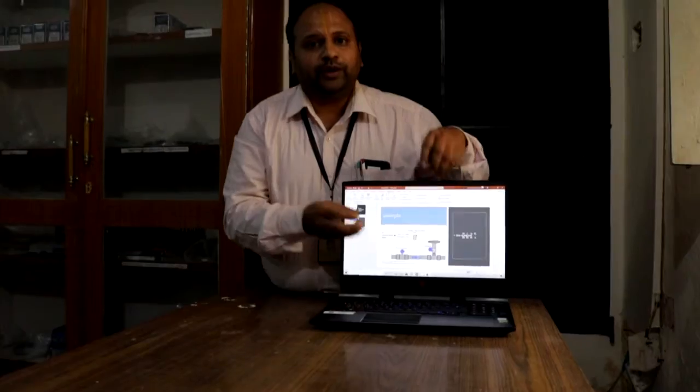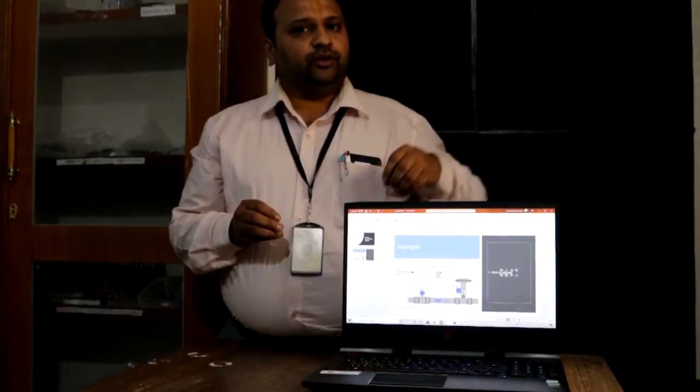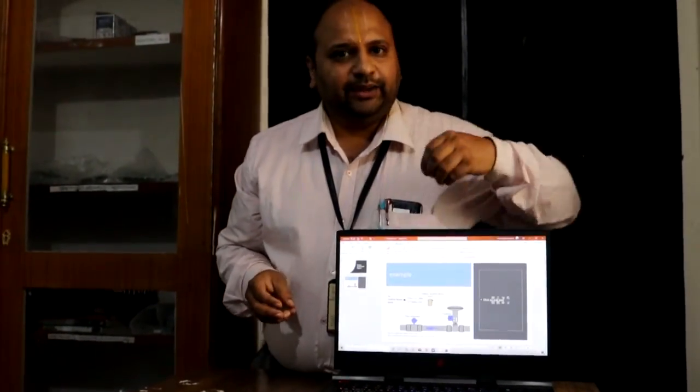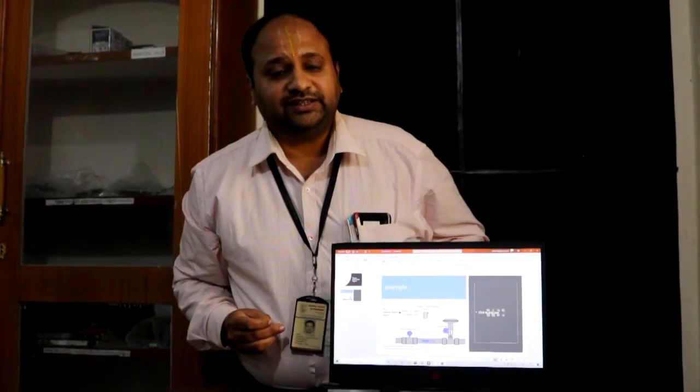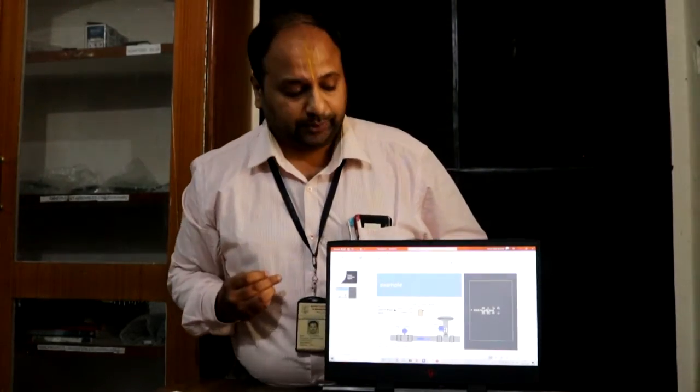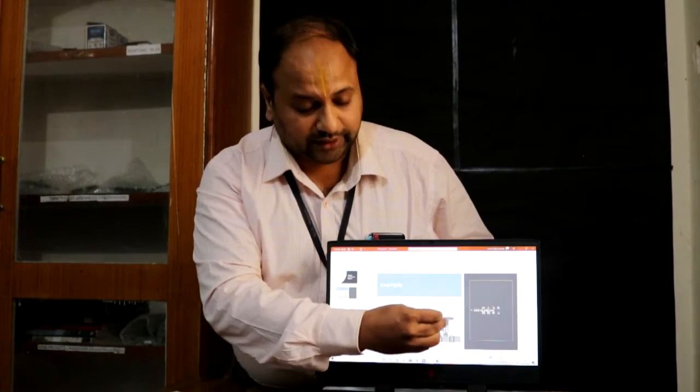When I give you an example, you should be able to classify the elements. Here, this flow sensing device, that is the orifice, plus this pressure converter acts as measurement. This controller will act as an error detector as well as controller, and this valve will act as an actuator and final control element. Okay, thank you.